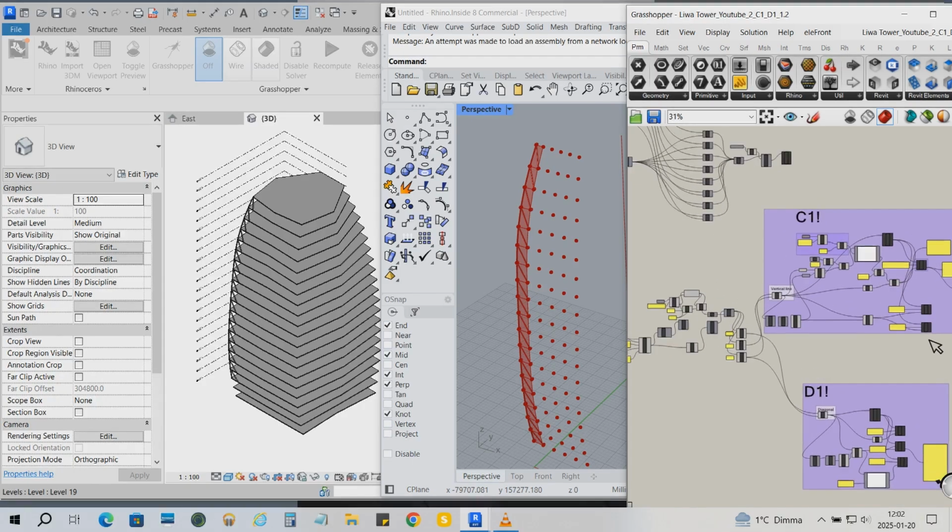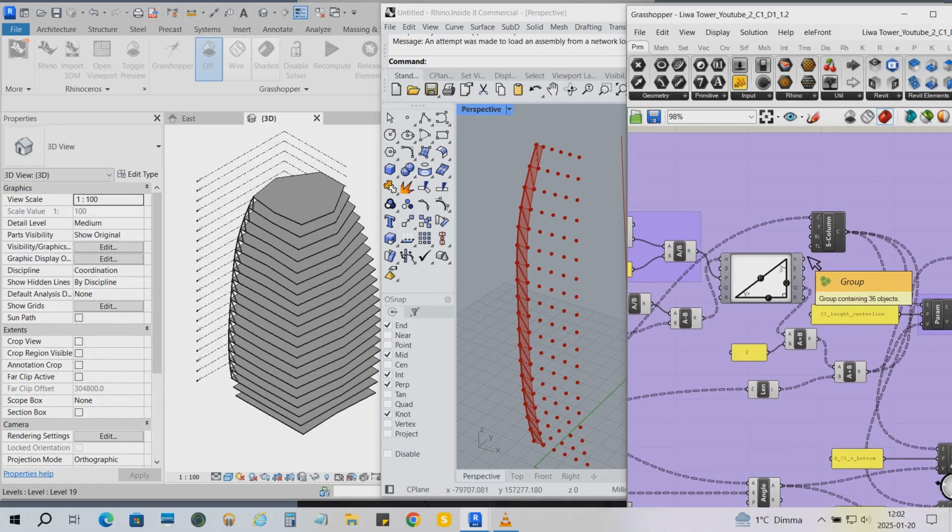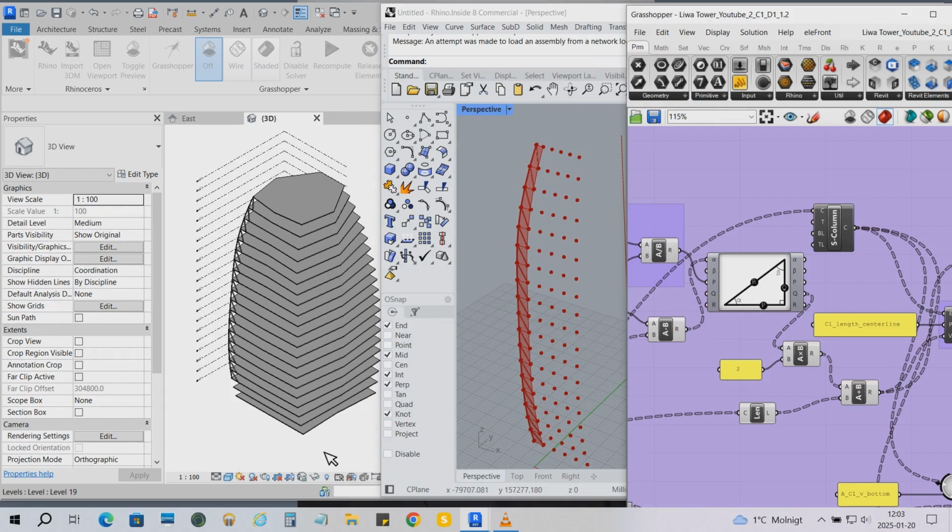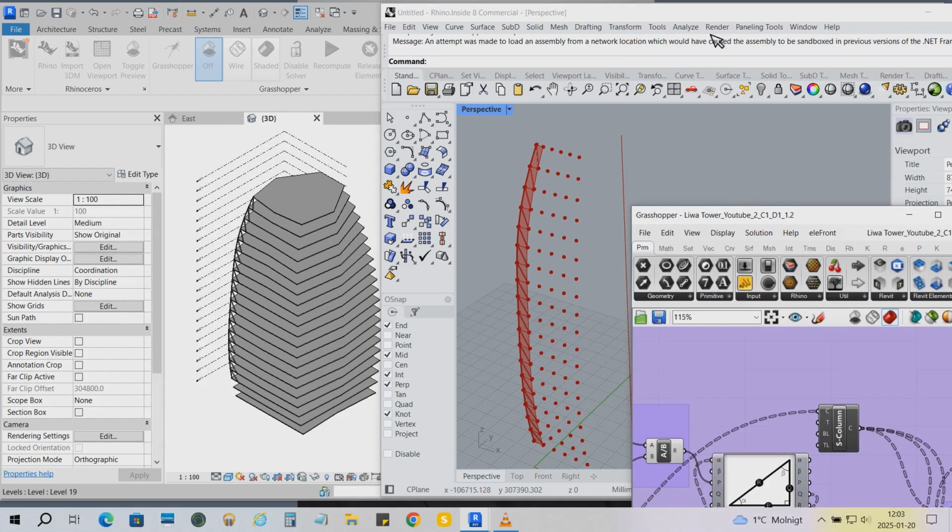You see here that we did some calculations, and that's because when we are moving the information from Grasshopper and Rhino to Revit, we are doing that through parametric families in Revit. And parametric families in Revit have their own logics and their own constraints, and they do not follow the logics of Grasshopper and Rhino. That's why we need to do some adjustments in order for columns to align properly, for instance, to the floor levels. I will show you what I mean.